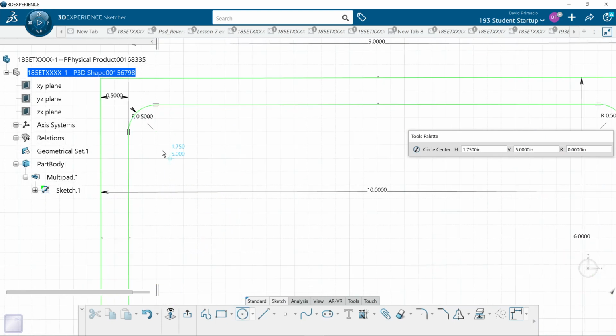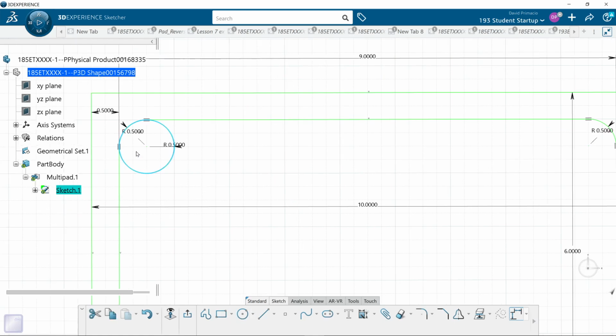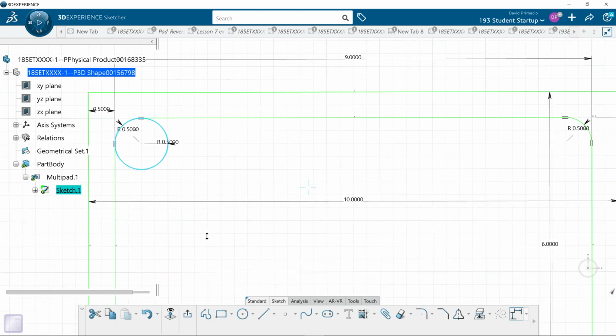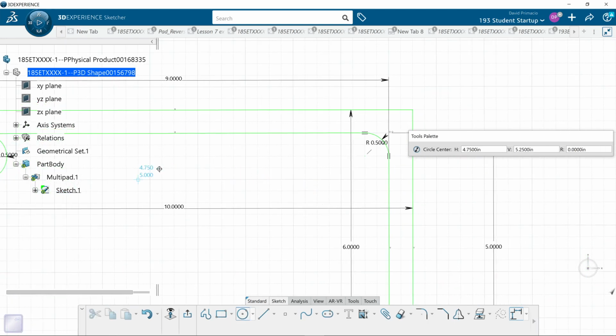And let's just say it starts at this point. If I'm using a 1-inch cutter, what is my radius? Half an inch. If that cutter goes into this curve and machines this, it's going to be perfect, right? It all looks perfect right there. No, it's going to chatter. Yeah, there's going to be some error, because... wouldn't you want to cut through it with a little smaller diameter?